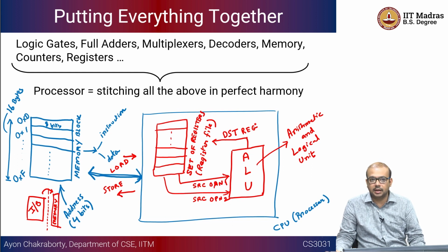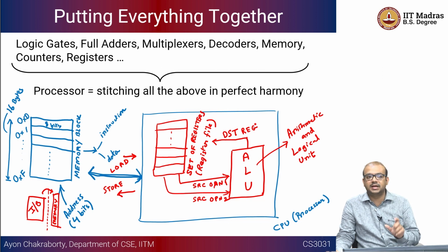add. Okay. So, if you have let us say 15 or 16 different instructions, you can encode them by let us say 4 bits, right, 2 to the power 4. So, you can have add, subtract, or, and, XOR, and a series of them. They can be encoded using 4 bits, but you also have to reserve some bits for mentioning what register is the source register 1, what register is the source register 2, which one is the destination register, and so on.